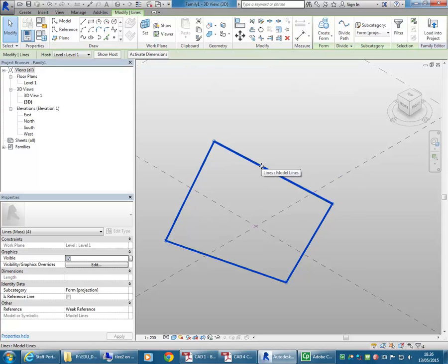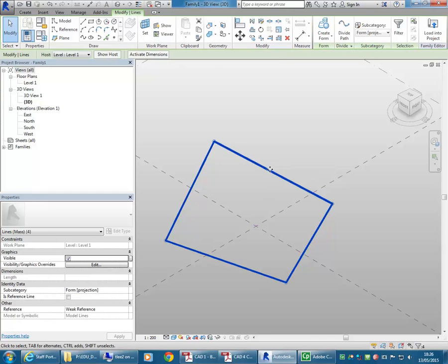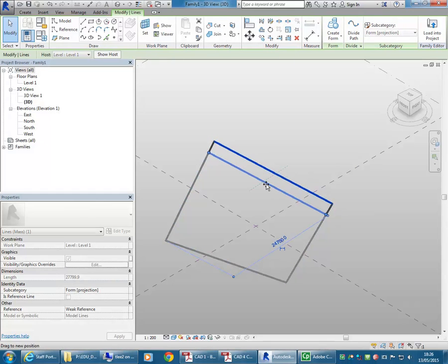and then you'll notice straight away, if you've mostly done solid modelling with Revit, that if you select any of those lines, it'll highlight, or often anyway, it'll highlight a group of them. And that's because it joins them together automatically, and when they're joined, it selects the whole group as a shape. If you want to select just one segment, you simply need to click again on the segment you want, and then you can move that separately.